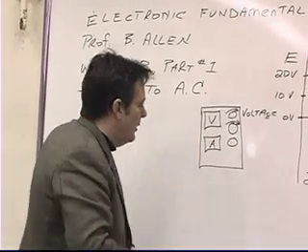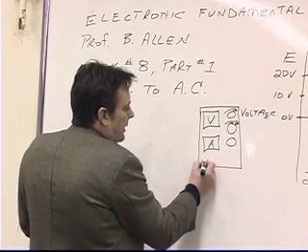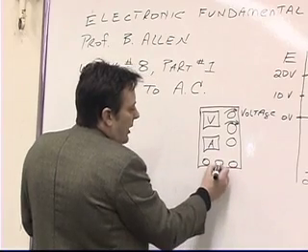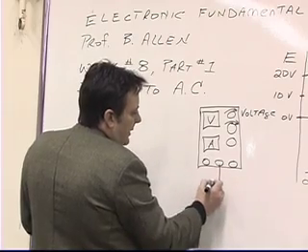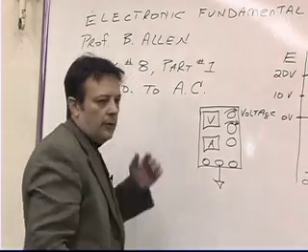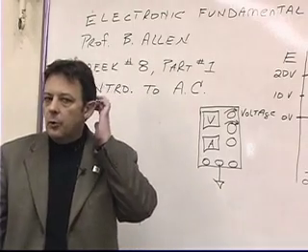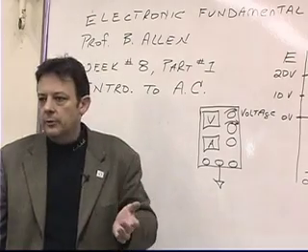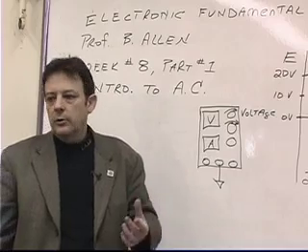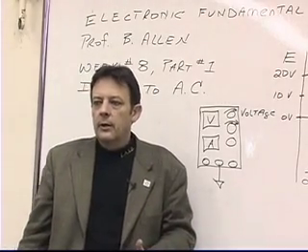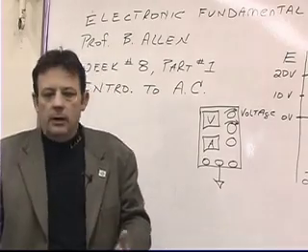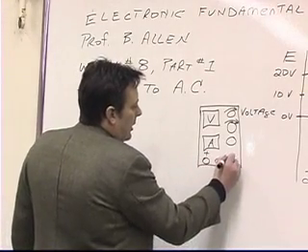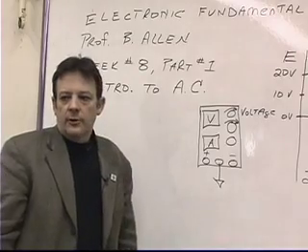Now, when we come down here to where the binding posts are, or where we actually hook on to the DC power supply, we find that the middle binding post is actually an earth ground. That's used for safety, and it's used in some experiments, not used in other experiments. You don't have to have a ground in a circuit for the circuit to work. Grounds really come out of a need for safety. So what we're going to do is focus on our positive terminal and our negative terminal on our DC power supply.